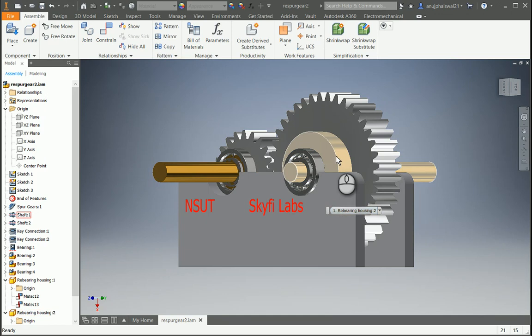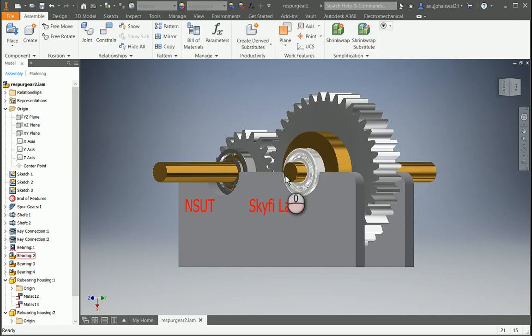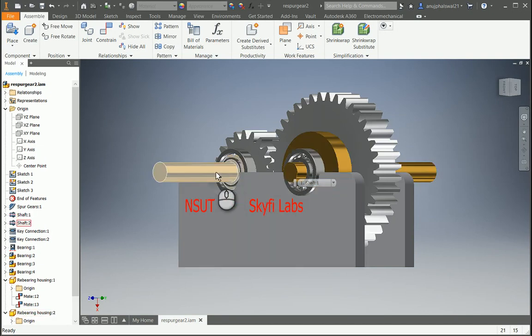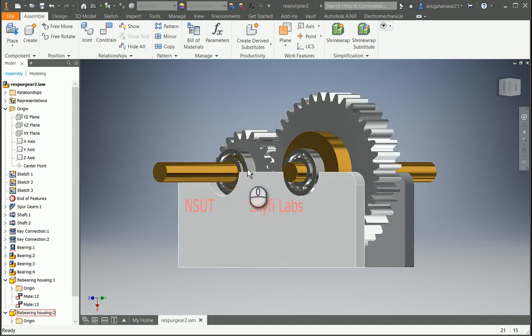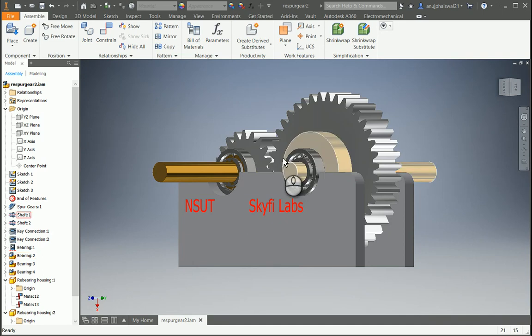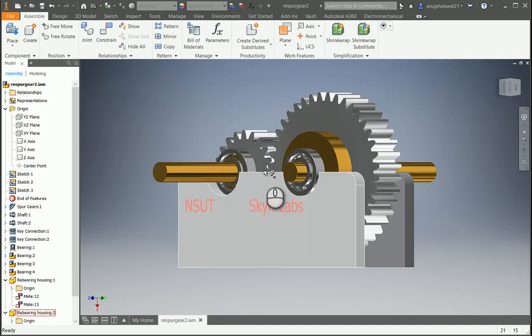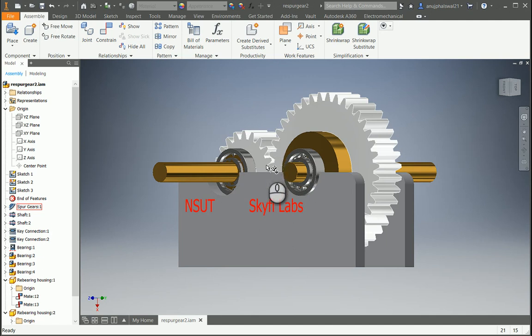They are used to reverse the direction of rotation between the driver shaft and the driven system. They can be used to increase or decrease the speed of rotation. Gears are also used to transfer rotational motion from one axis to another. The two gears are rotating in opposite directions, the smaller gear is spinning twice as fast as the larger gear, and the axis of rotation of the smaller gear is to the right of the axis of rotation for the larger gear. The gear material should be strong enough to prevent tooth breakage, hard enough to resist contact stress, and ductile enough to resist shock load.